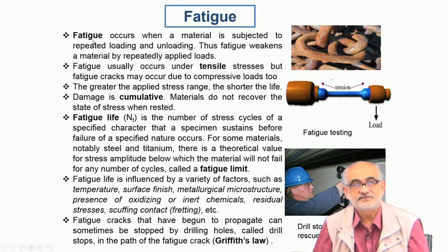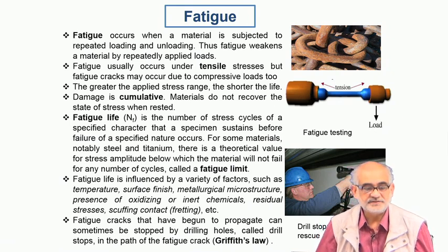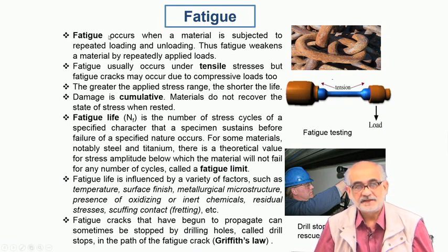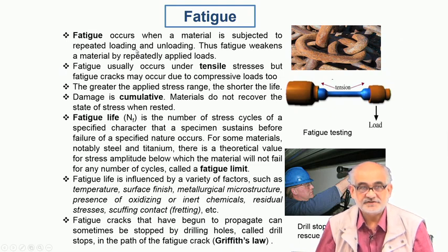So obviously, when a designer designs a component only based on the yield strength or the tensile strength or compressive strength for that matter, that may not be adequate, because if the component is likely to undergo repeated cycles of loading and unloading, then the material eventually may fail at a level of stress which is lower than the design limit.